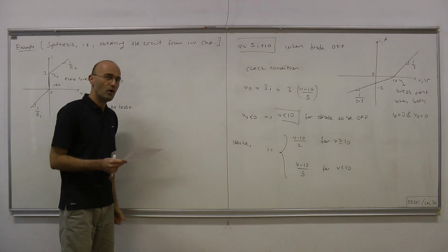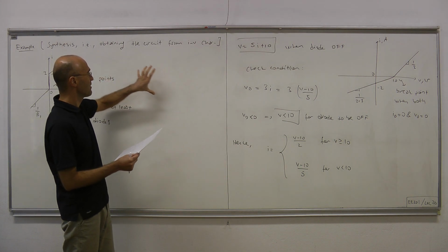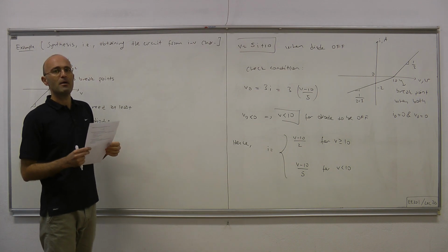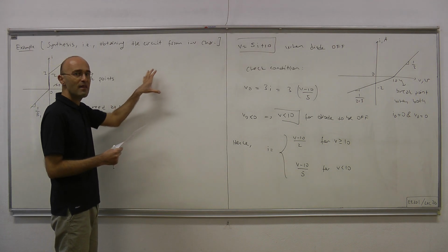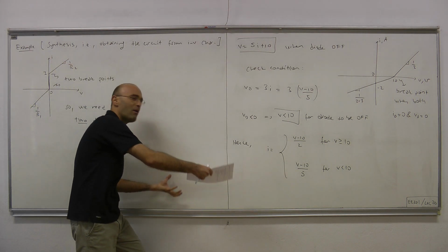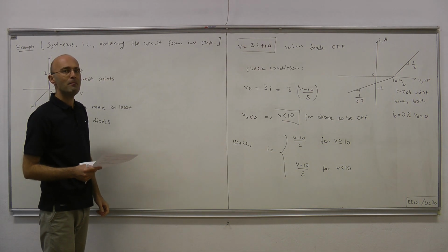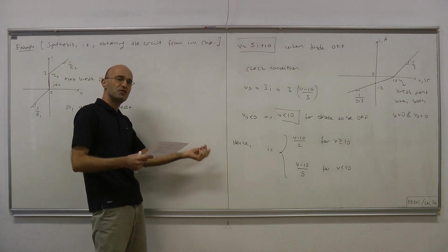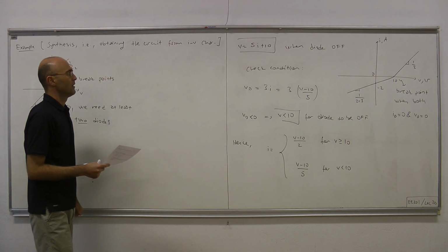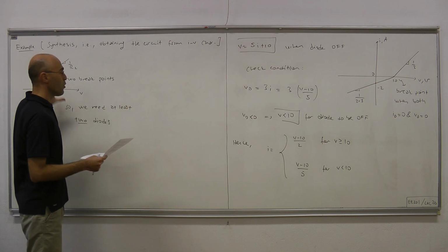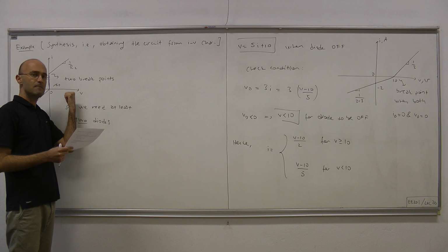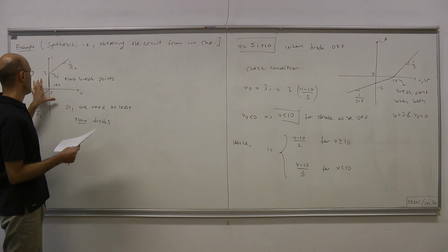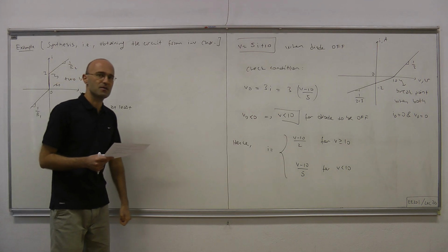We do that on and on until we realize that a curve belongs to some particular circuit that we're familiar with. Then we combine all the pieces from the bottom up, in series or parallel summation depending on how we decomposed the curves, and we reach the final one port that generates the given IV characteristics.